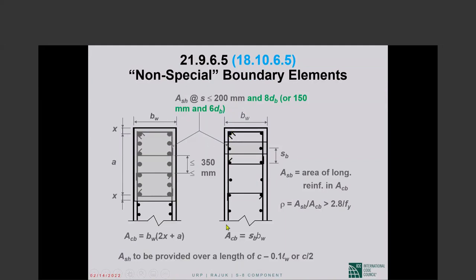If you have distributed reinforcement, the reinforcement that we need for flexure and axial load, we decided to evenly distribute throughout the shear wall cross section, that we sometimes do for rectangular walls that are low rise, then the local reinforcement ratio is simply the area of 2 bars divided by the spacing. Okay, as simple as that.